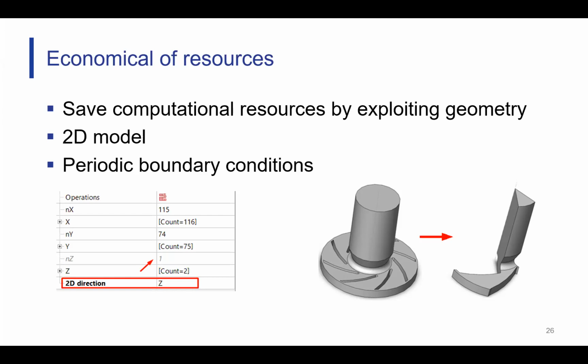And this is why in some places, if you set up your initial grid so that the domain is just one cell, you're still going to lose this property as soon as you refine it, because in the region of refinement, it's going to be 2 cells or more. With FlowVision, setting up a true 2-dimensional case is as simple as just specifying the dimension that you want to exclude, and you greatly increase the speed of your calculation.